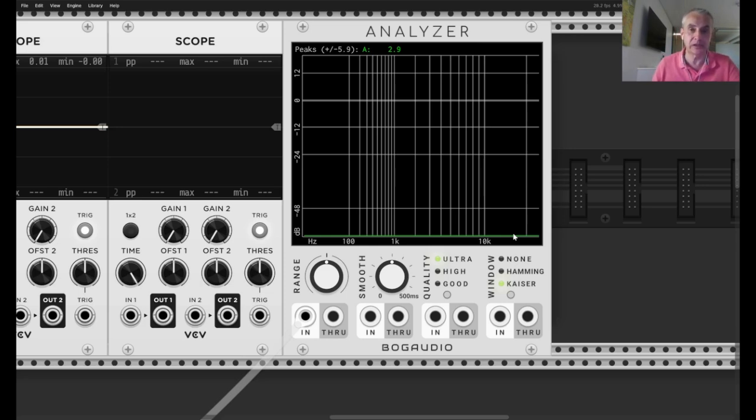So the output in the digital world would be that the sawtooth wave will have frequencies in there of harmonic sine waves that cannot be sampled back to the right frequency and therefore get sampled back to a wrong frequency. That frequency is called an alias. And let me see if I can make that audible.